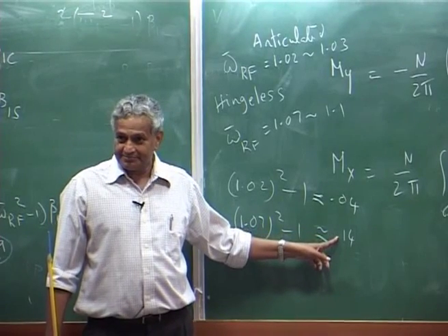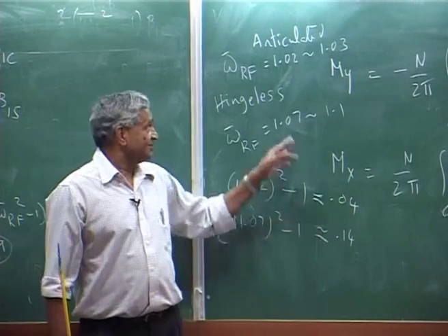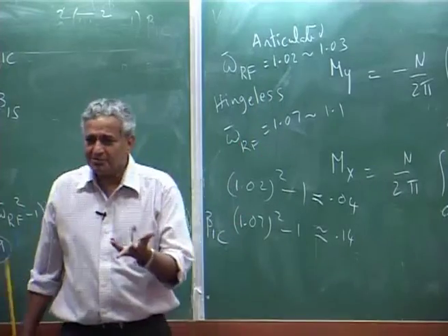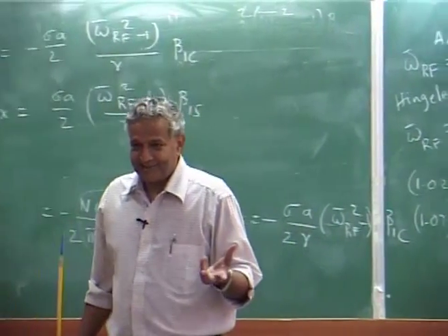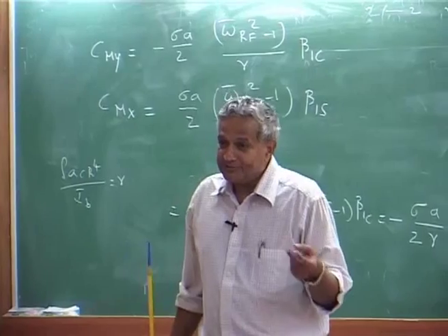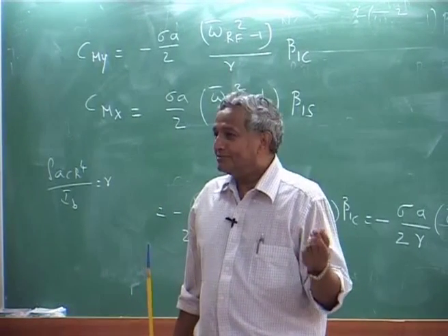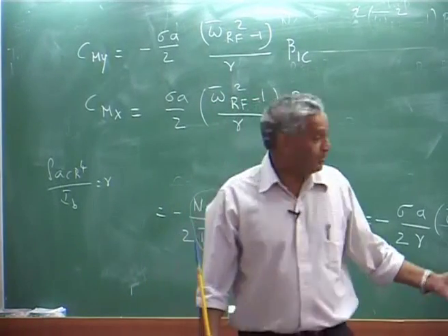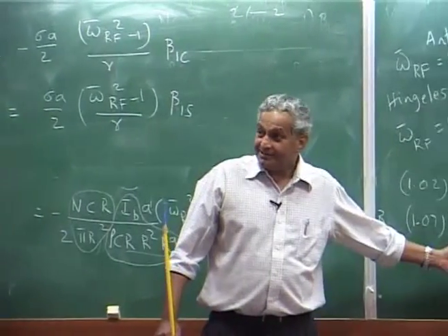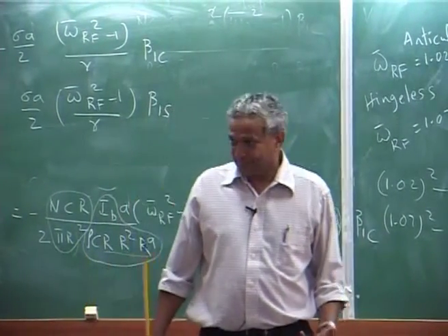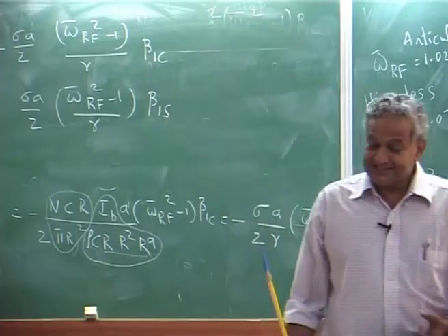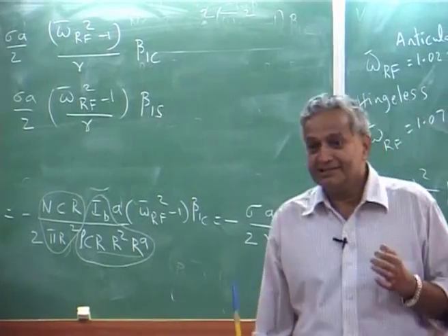Three times the change, whereas flap frequency changes, you say, only 5%. I have changed my flap frequency by 1%, 2%, but I change my hub loads like 3-4 times. Follow? This is a very, very critical thing in the helicopter.